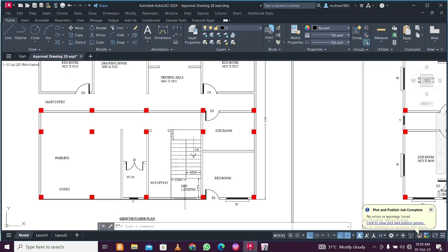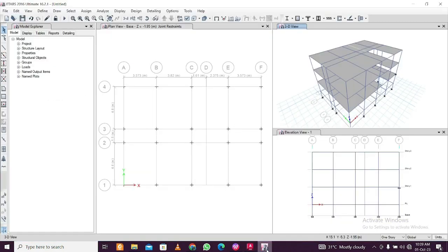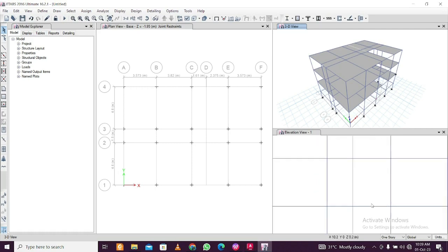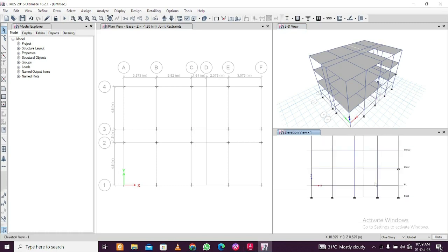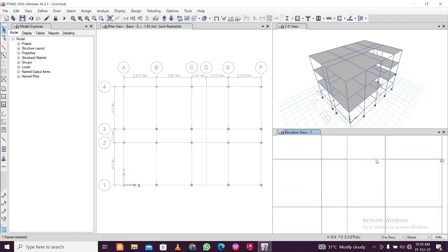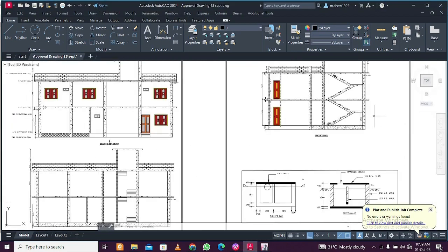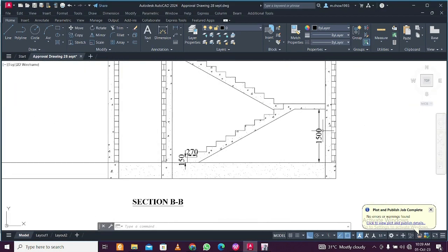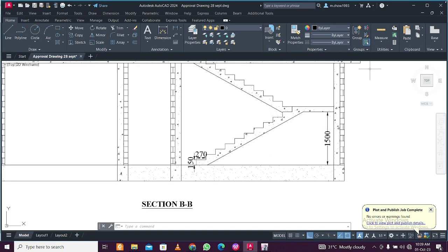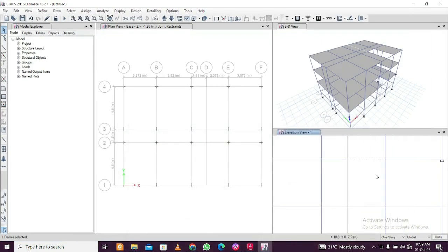We will see in the architectural plan, you can see the mid landing will come in this particular portion, around here in this grid, that is grid 1. So you can see grid 1 is here, and if I select this particular beam and copy it down below, then I can create this. So let's find the height where the staircase mid landing will be. It is a dog leg staircase, so it will come at the middle, around 1.5. So if I can do this offset at 1.5, then I'll be able to make the landing beam.